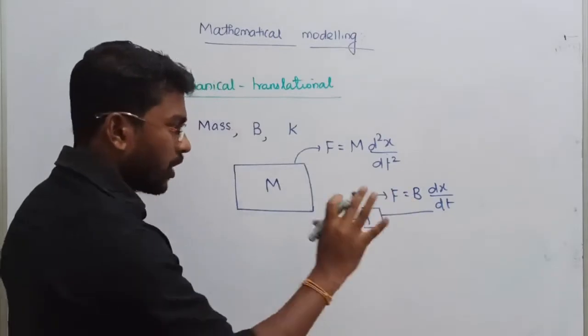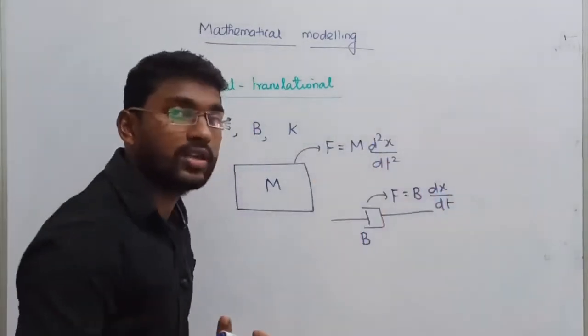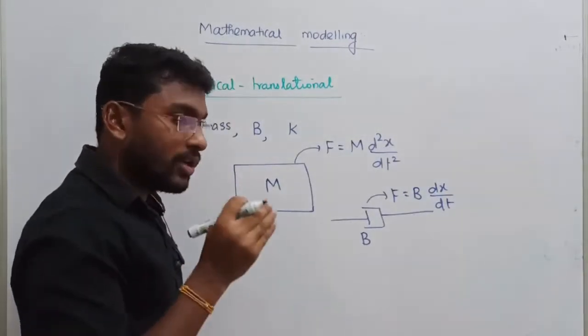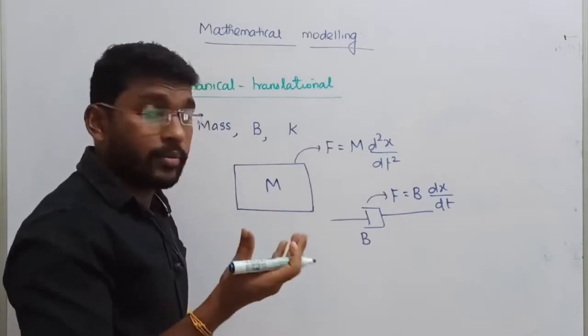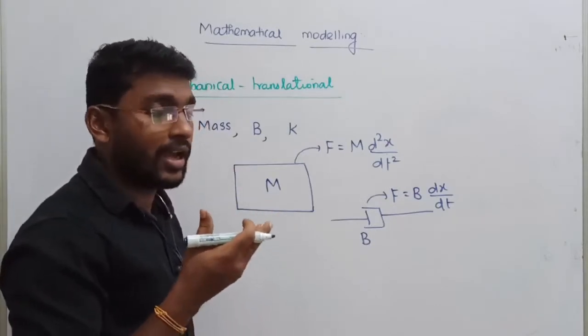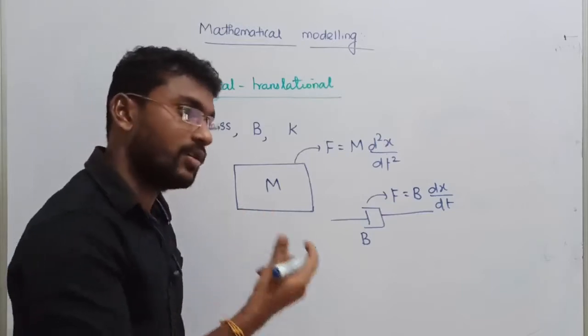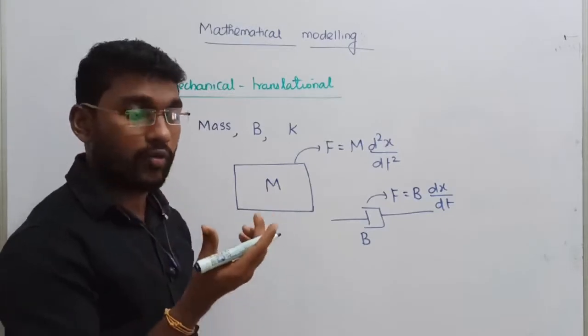So we are observing that from the mechanical domain we have some properties, and I am going to shift all those things into the electrical domain. Then you can play. In the electrical domain, once you get the relation between the mechanical domain and the electrical domain, then we can write the mathematical equations and apply Laplace transformation, and then we can identify the corresponding poles, zeros, and you can locate them wherever you want. You can find out the range of k.